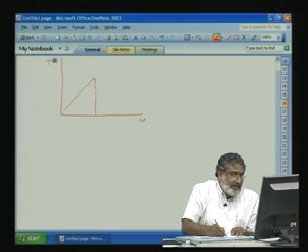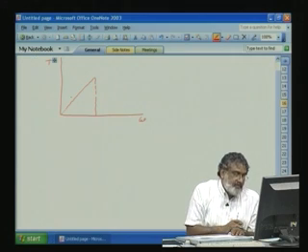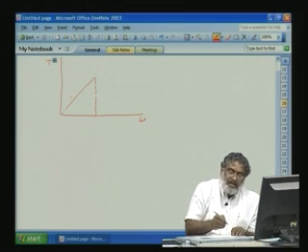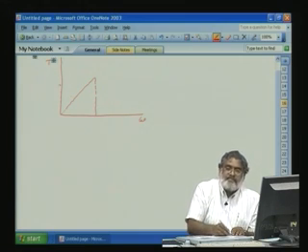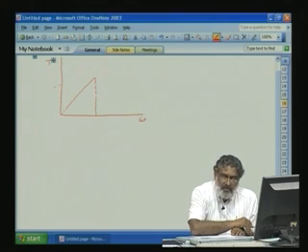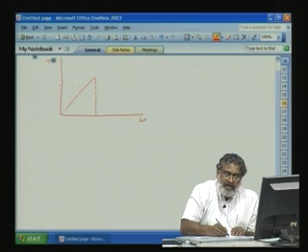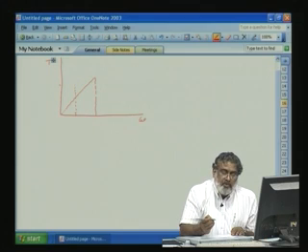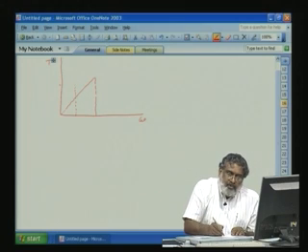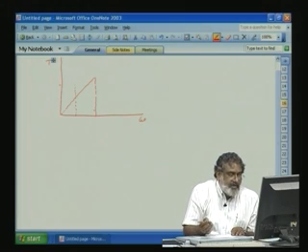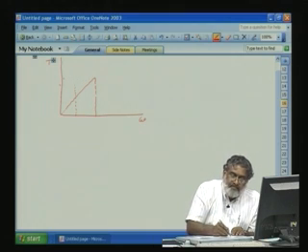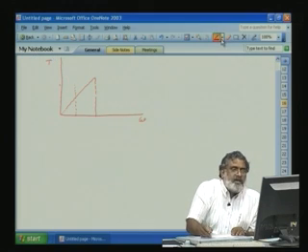Now in this region, suppose this is torque, depending on the current the torque can be anywhere. So for the same speed, we can have any torque point here depending on the current. So with the voltage, suppose at this voltage here, omega here, let the machine be taking the maximum torque, that means current is maximum. So torque is also maximum here, we will mark the maximum torque here with a different color.